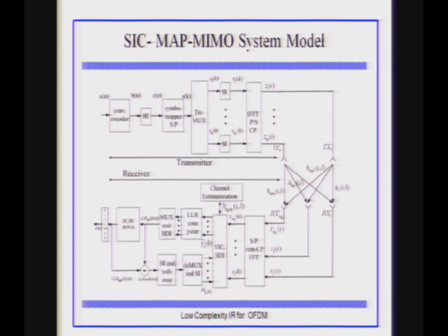Now, we just talk about extending the same scheme to MIMO, where we have one more interference to worry about, that is the co-antenna interference. So quickly, the generic MIMO system: you have all these symbols coming in and getting onto NT spatial streams, and they get transmitted across NT transmit antennas, and you have a channel that is kind of a matrix, and that gets back, and now you do the reverse operations as we saw before.